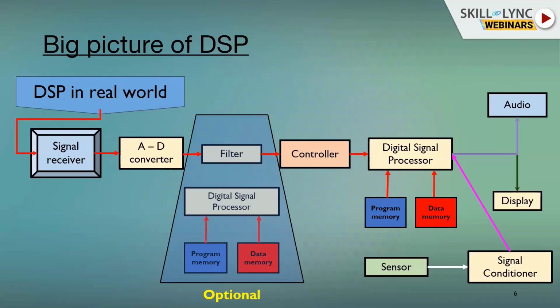It means that you have a limited amount of program memory that can be up to around 1 MB or 2 MB, and data memory can extend up to 64 MB, just as an example. What this does is speed up your operations, because it has a constant memory that is addressable, right? You don't need to fetch the data from something like RAM. You have everything in the program memory, within the controller itself. So this accelerates all the computations. This is one example of a digital filter.